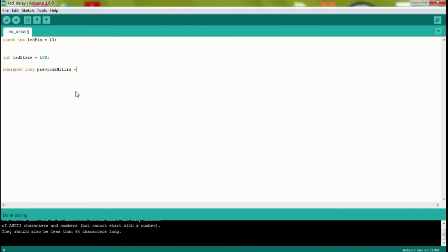Every Arduino program must have two methods in it. The first one is void setup. Its content goes inside brackets. The second part is void loop, which must exist but can be empty. The first one, which is void setup, determines things that will be done once at the beginning of the program, and the second, or void loop, will tell the board what to do continuously in a loop forever as long as the Arduino is on. The second method's job is what is normally asked of Arduino.